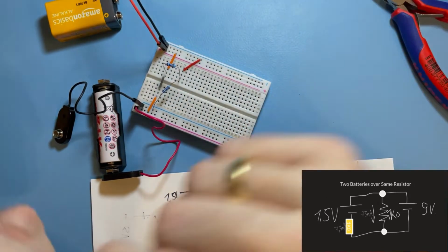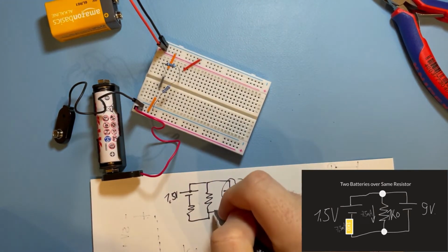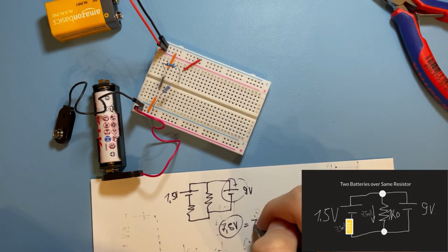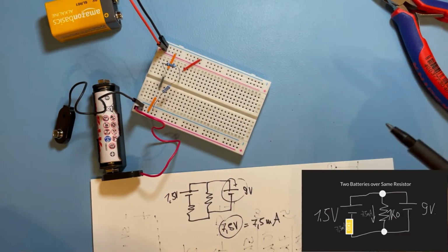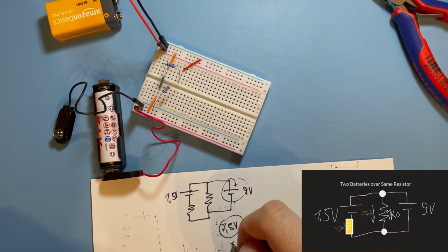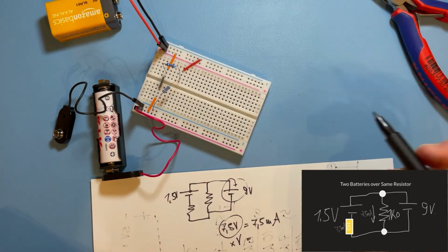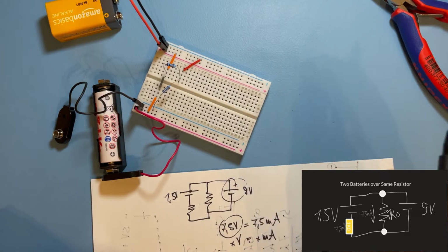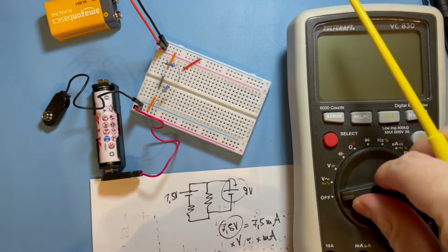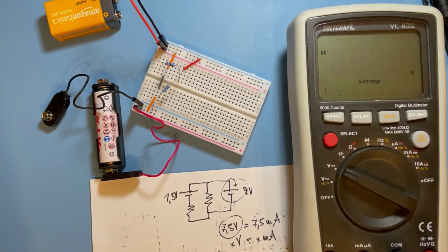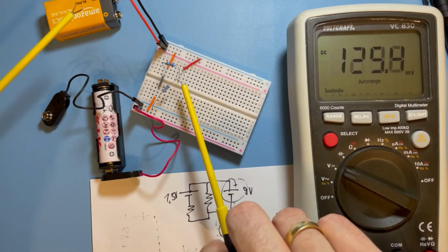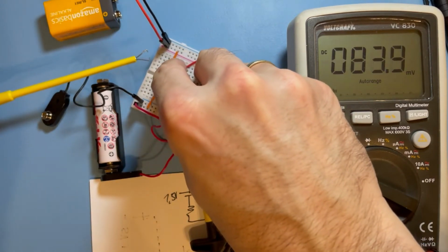So we can either measure now the current that is going through these resistors, or we measure the drop. A drop of, let's say, 7.5 volt across the resistor would mean 7.5 milliampere. That's the specialty of a 1K resistor. No matter what, let's say you measure X volt drop across the resistor with your meter, you know there are X milliampere flowing through it. You can put it here to see nicely. Put it to measuring volts. Put it across the middle one. Let's say here.